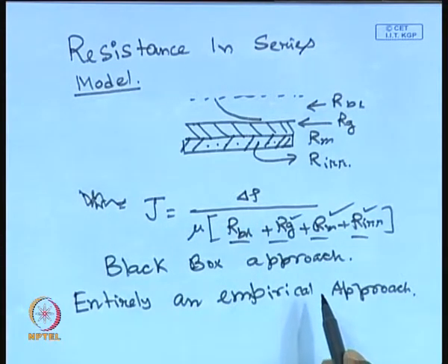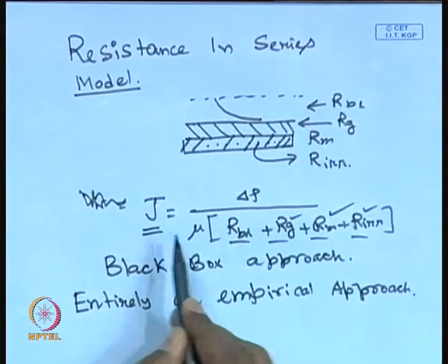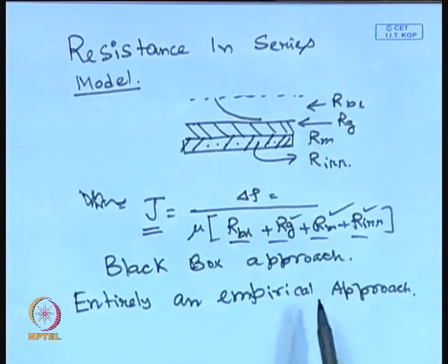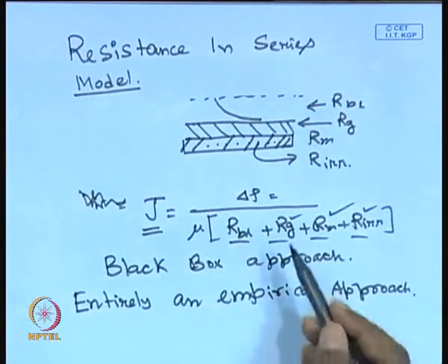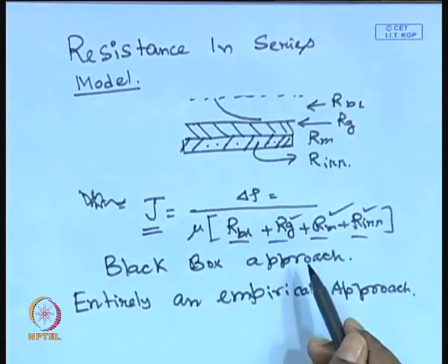in a laboratory scale, let us say around 10-15 experiments, and then fit the flux decline data with the operating conditions empirically, and then that will be inserted into the model, and that model can later be used for scaling up under the same range of operating conditions and with the same fluid or effluent. So, in that case, the resistance in series model becomes quite handy.